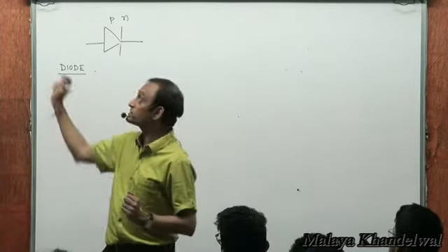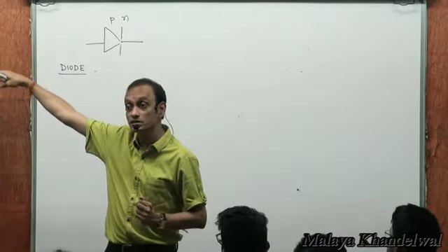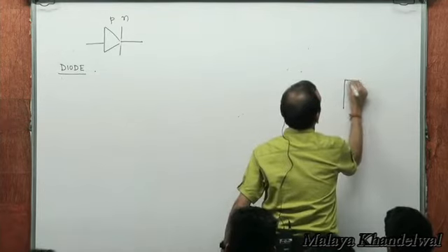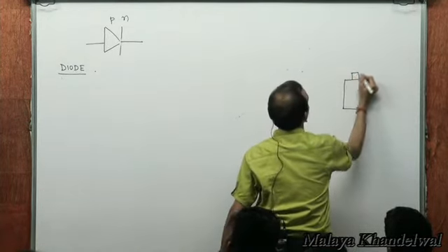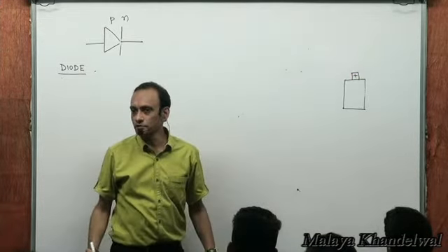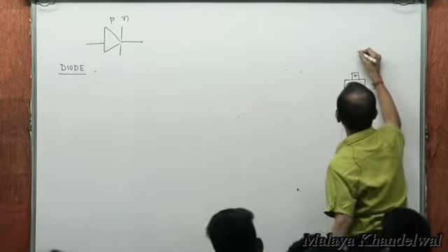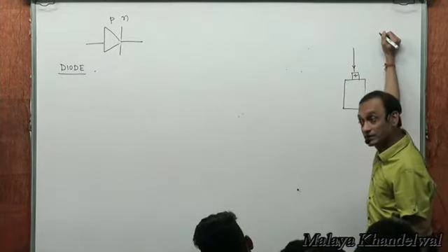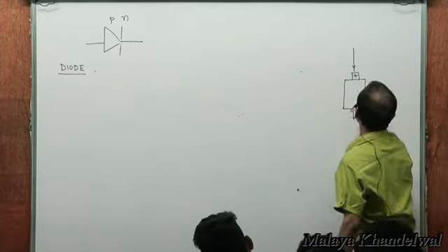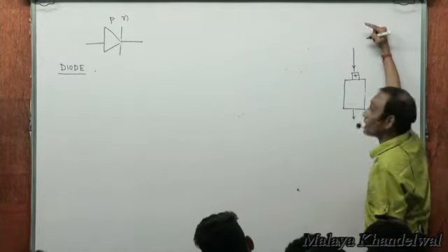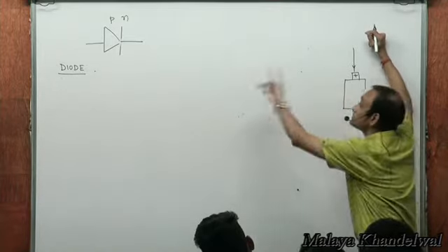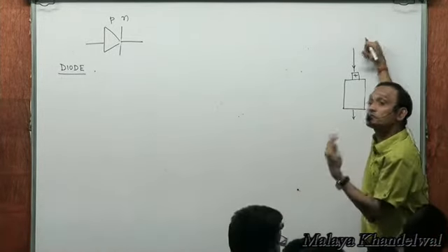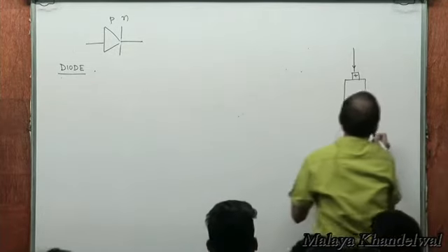That means if you connect a device here, if you want to charge, let's say, your phone battery directly with this, what's going to happen? This is your phone battery and you want to charge it. This is the positive terminal, right? How will a battery get charged? If current flows in this direction, only then it's going to get charged. Yes or no? If it flows in the opposite direction, it will get discharged, right? So now, if I had to take an output directly from there and connect it to this with the hope and expectation that this is going to get charged, no. I'm going to get it in only one half of the cycle.